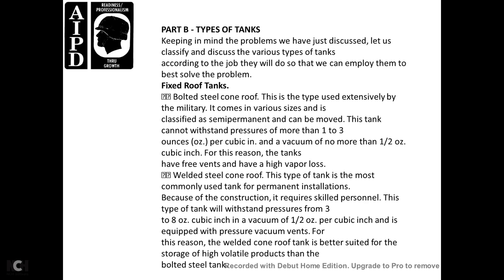It can be moved. The tank cannot withstand pressure of more than 1 to 3 ounces per square inch, or vacuum of more than 1/2 ounce per square inch. For this reason, the tanks have vents and have high vapor loss.